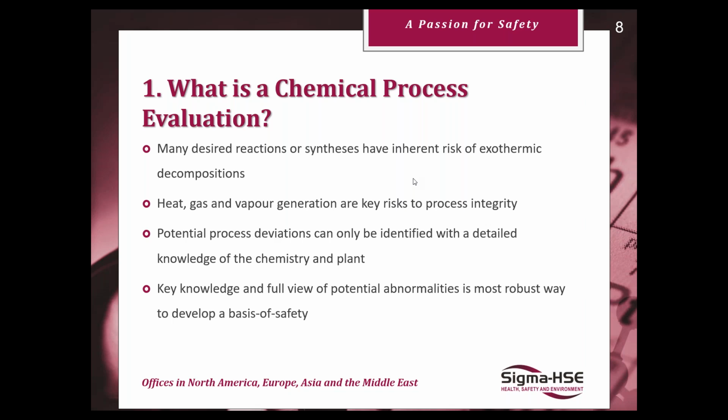So that's not just looking at what happens when you do your desired reaction, but what happens if for some reason things run out of control, or a reactor is subjected to a sustained fire and heated up externally. Your material might start to decompose itself and generate its own heat in that case.